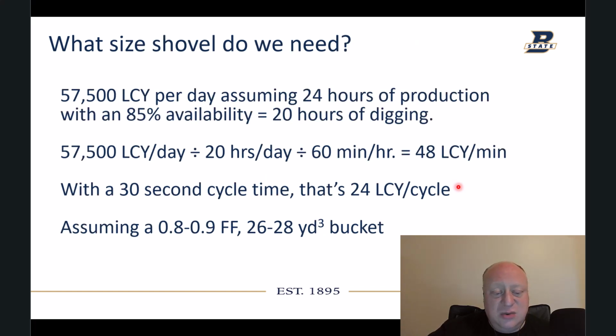And so what size shovel do we need? Here's how it goes. I took the bigger number, the Southern Reserve, which is a whole lot more than the North, and assumed an 85% availability. So 24 hours of production, 6 days a week, but with 85% availability, that equates to about 20 hours of actual digging time, right? And we know our loose cubic yards a day.